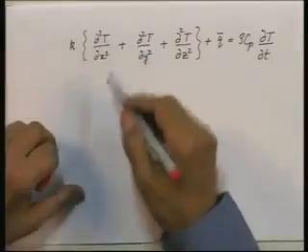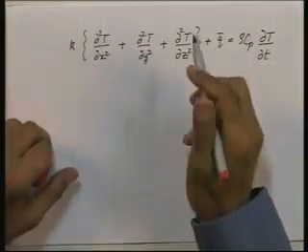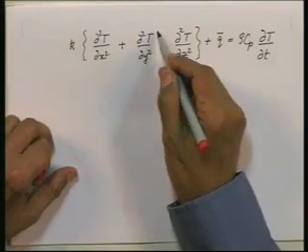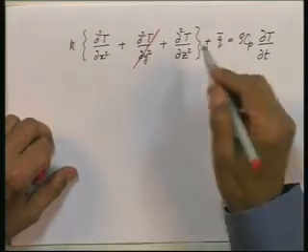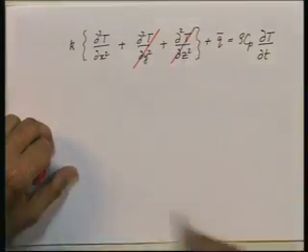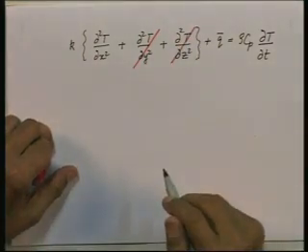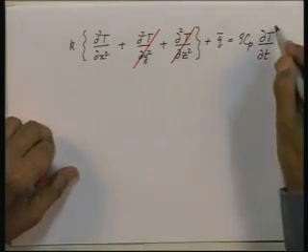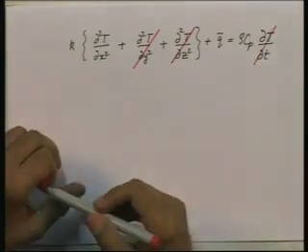Now, in this particular case, because it is an infinite slab, there is variation only along the width, which we call the direction x. Therefore, there will be no variation in the y direction or the z direction. We also know that there is a steady state, therefore the term dT/dt is equal to 0.